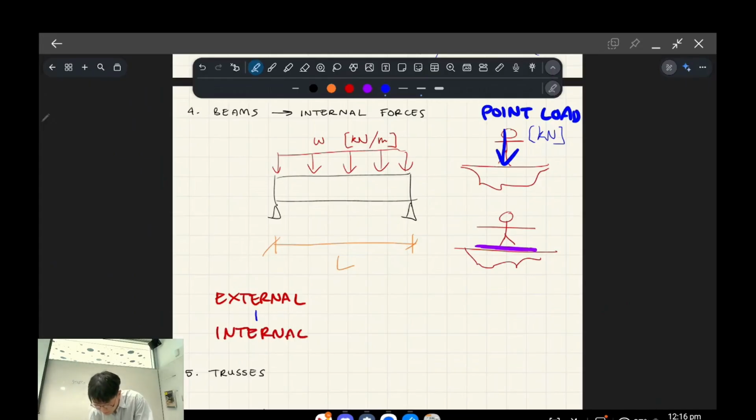And if you have equilibrium, you've got this object and it's got external forces being applied on it, which in this case is the distributed load. And then in itself, it's generating internal forces to balance that out so that it doesn't move, okay? That's where you get this concept of beam internal forces from. And that's the stresses inside the beam trying to react to the external forces. Does that kind of make sense? There's a lot of concepts I'm just pulling out of thin air, but you just gotta trust me for now. I'll explain them a bit more as we go.